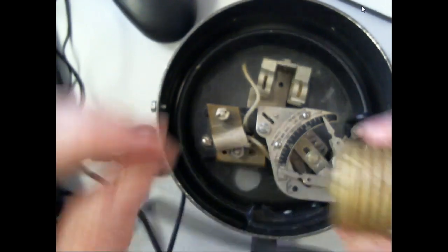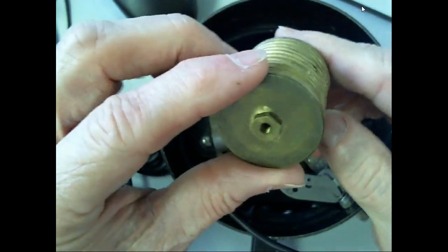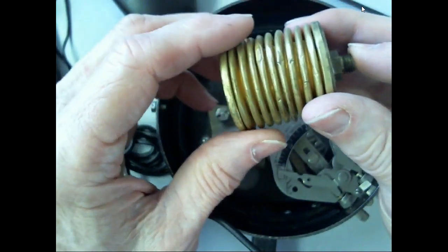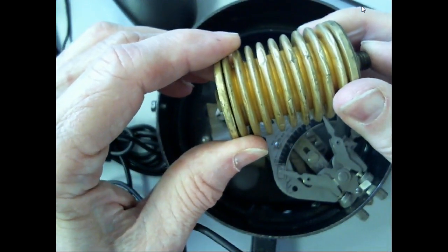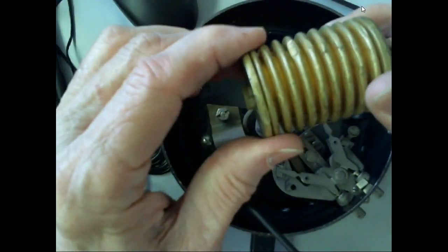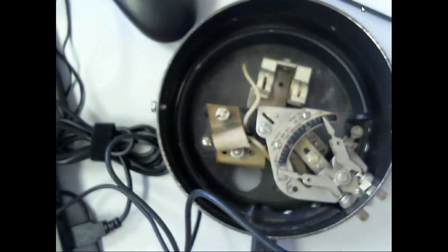So this was another sensor. We'd have to combine this with something else. This is called a bellows. And so what would happen is we put pressure on this side and it would cause the bellows to do what? Expand. And then we could set like a limit switch or something up here. When it hit it, it would indicate we hit a certain pressure. It would drop down below that. And we do have solid state stuff. So this is the bellows.